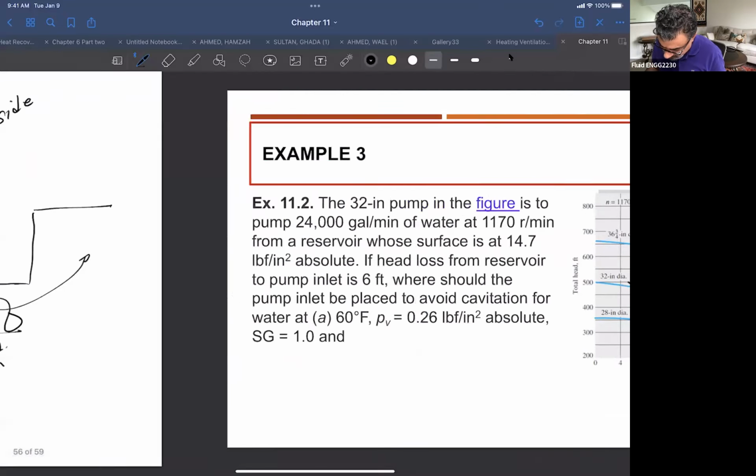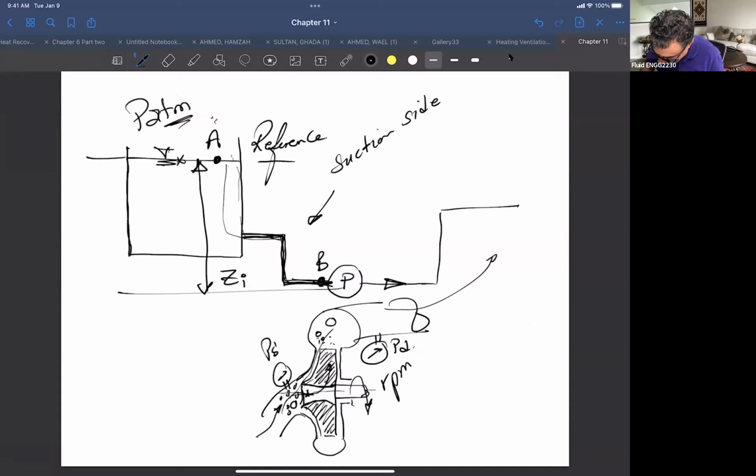So in this case, those bubbles will collapse because the pressure here is increased, right? And what will happen is you might see fluid jumping into this cavity, and of course this is going to be happening all the way here, and that's why you will see lots of impingement, like the liquid is hitting the impeller casing.